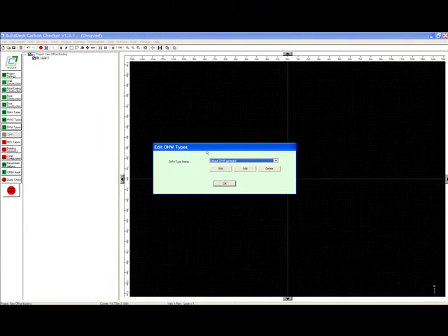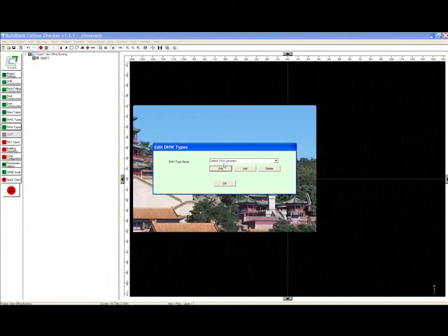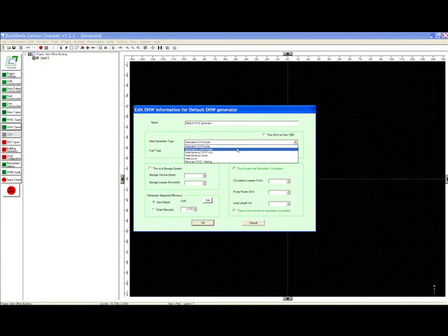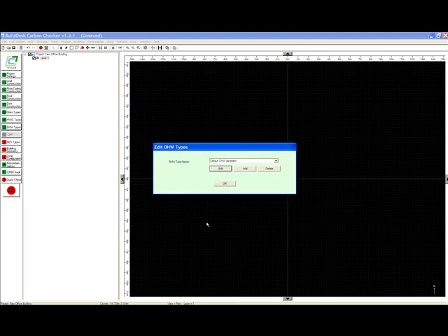We'll have a standalone system, and we're going to have an electric system. And because it's a new build, it's post 1998. And we have the option to have a storage system, but this one isn't. Once again, we can either get the seasonal efficiency or we can enter it manually, and that's what we'll do here. And then we'll click OK.